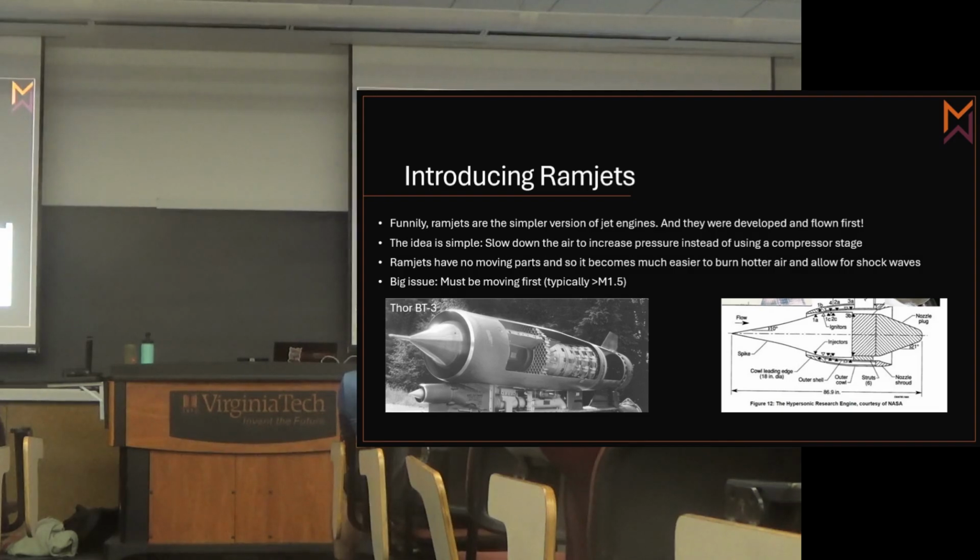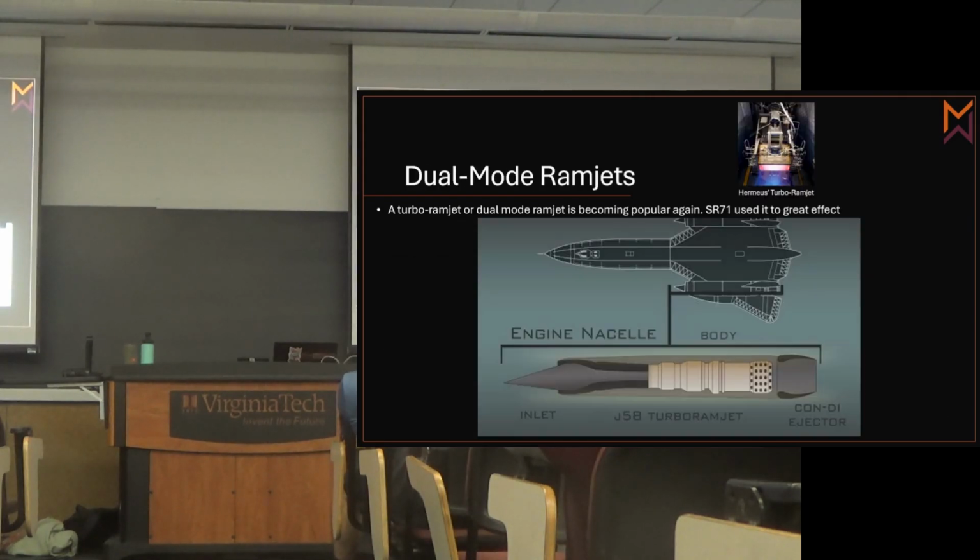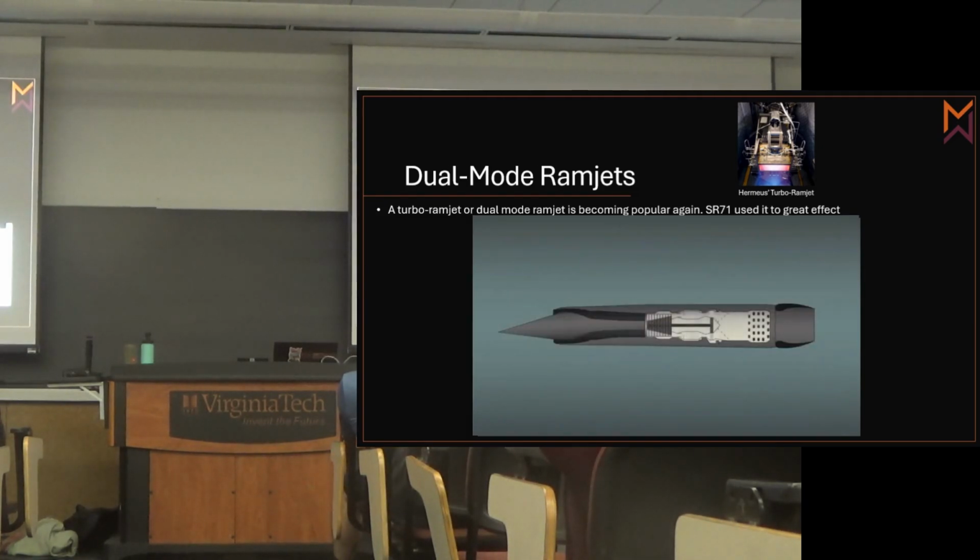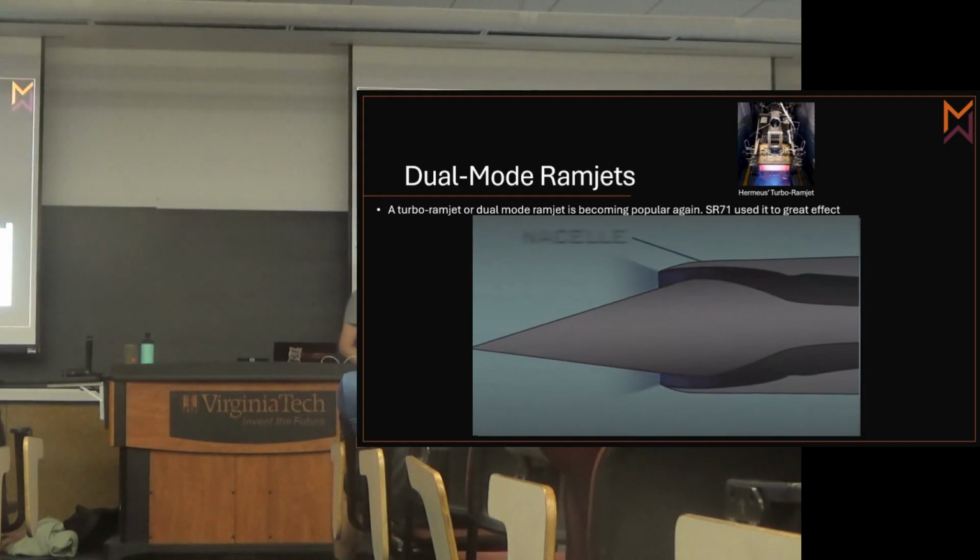So you can see this guy here. Shock up to there. There's actually another shock right here. And then remember, converging ducts, when you've got hypersonic air, they don't speed up, they slow down. So this is going to actually slow down until it goes under Mach 1, and I have a normal shock right there. Because you can see how this changes from being a converging duct to being an expanding duct. So what should happen is I should get a normal shock right at the throat of this, and as I go past this, the flow will continue to slow down until it goes into this combustion chamber. I don't know if that made sense at all.